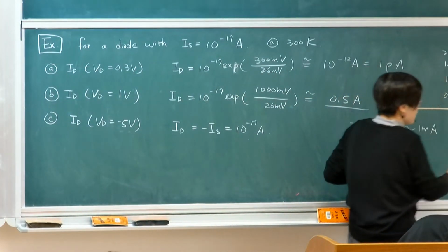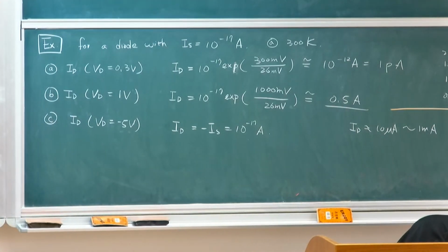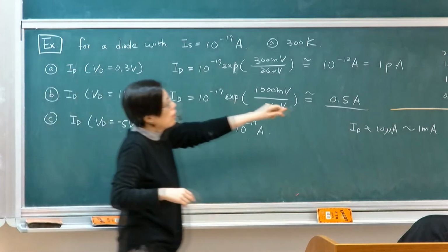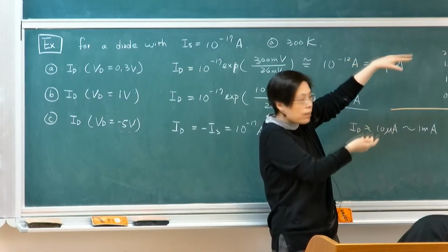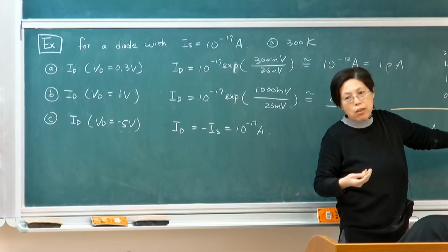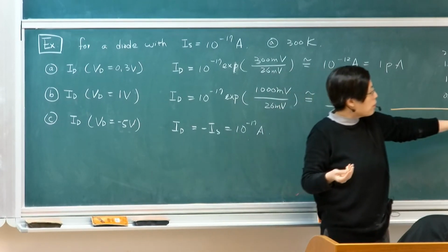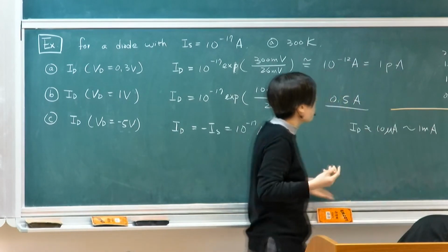So instead of having an exponential current model which gives you an IS, I'm just going to give you a VD-on. For example, if you're using this equation, I give you an IS, and then you do the plot, and you size it to the range where your circuit would operate, and then you can extract something called a VD-on, where it looks like your turning point.